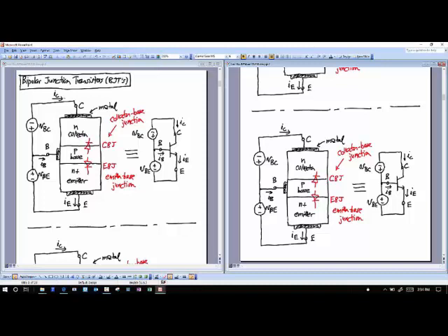So if it's PNP, of course, I'm going to want to change these. I'm still going to have a collector, a base, and emitter, but actually, for PNP, the emitter has the higher voltage. Okay? So think of this as the higher voltage being at the top and the lower voltage being at the bottom. That's usually always the way you're going to see it for circuits. When we actually attack circuits, which we haven't yet, that's how you'll see it. So up is the high voltage, low is the low voltage.